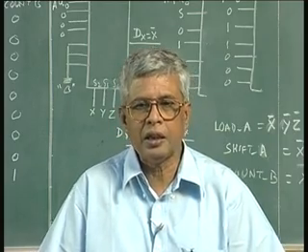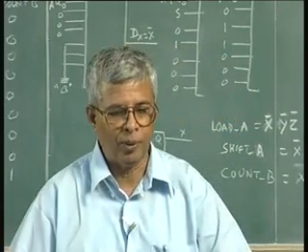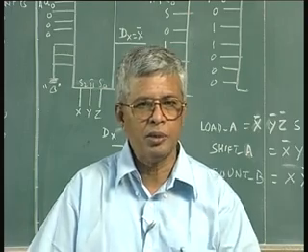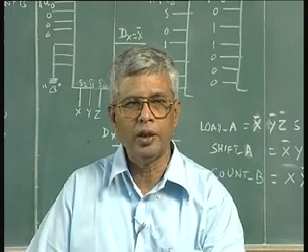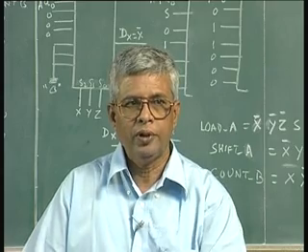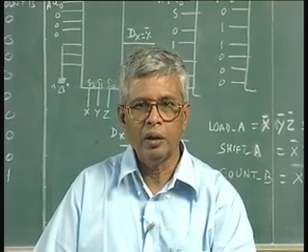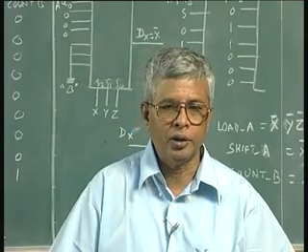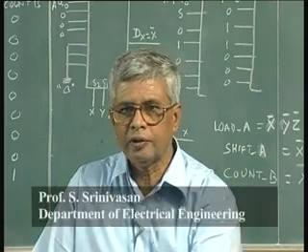When you say sequential circuit, it is not necessarily only the sequential building blocks like flip flops and counters; it can also have a driving combinational logic. The total system is sequential. That means you have a sequential system which goes through a sequence of states, but when it goes through that, it will be driven by combinational logic. So, the steering logic is combinational, and the total circuit is a combinational and sequential combination.